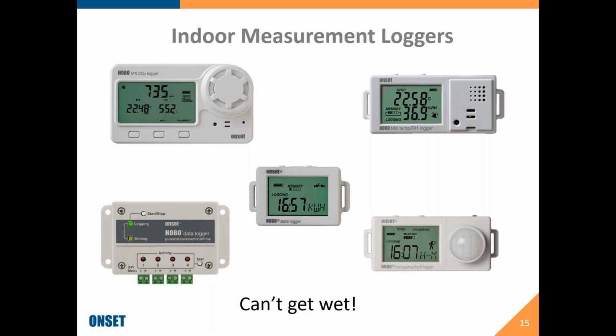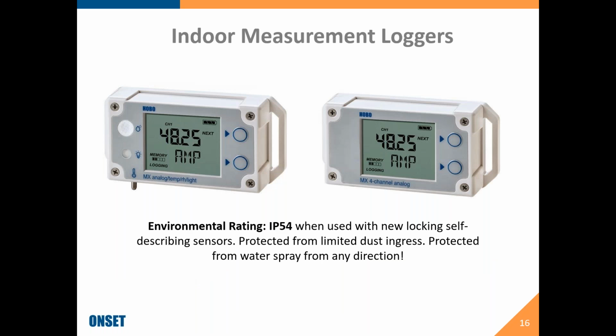You've got 4 channels: light, occupancy, temperature, relative humidity, the change of state, the carbon dioxide measurements. Most of these data loggers do have this IP54 rating, which means they usually can be exposed to dust, but they can't be sprayed down from getting wet.